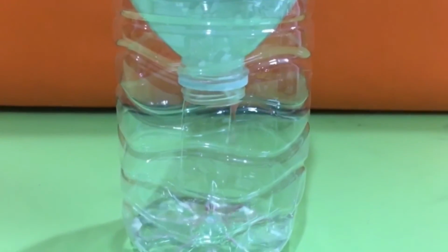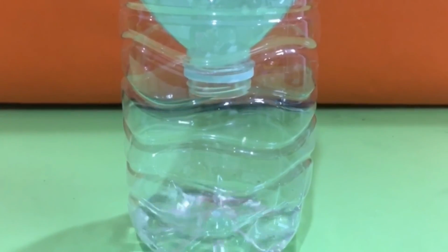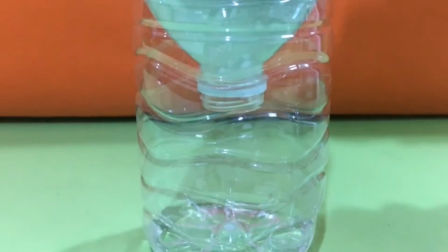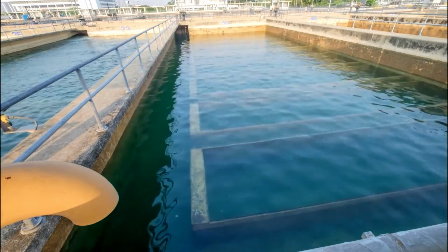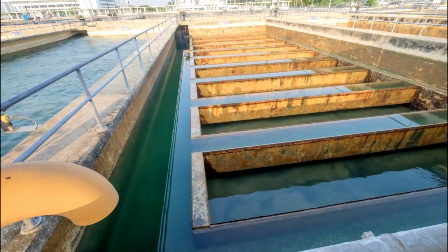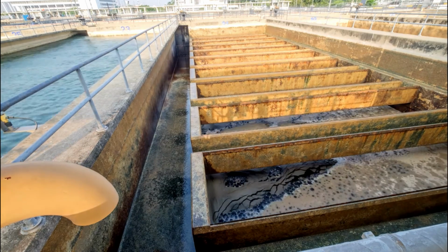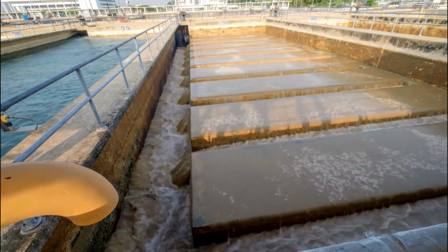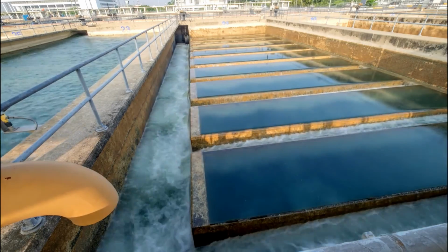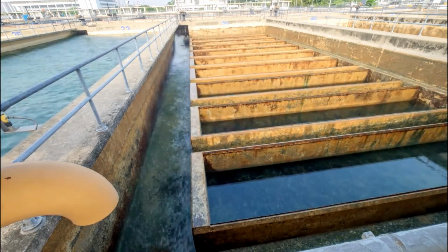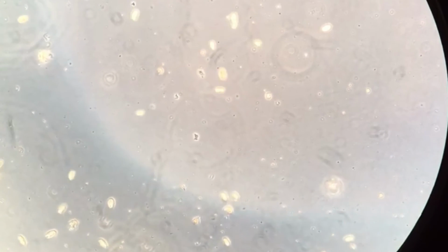Slow sand filters are effective at removing larger solid particles such as coarse-grained sand and gravel in wastewater. This type of mechanism is also good at removing turbidity, odor, taste, manganese, and arsenic in a single treatment step. This method is important to improve the wastewater. Besides, slow sand filters also filter out most of the microorganisms such as bacteria, viruses, and organic matter present in the wastewater.